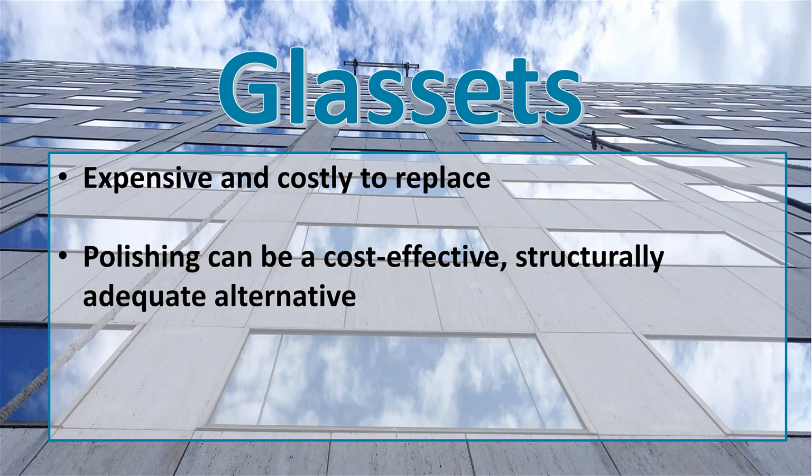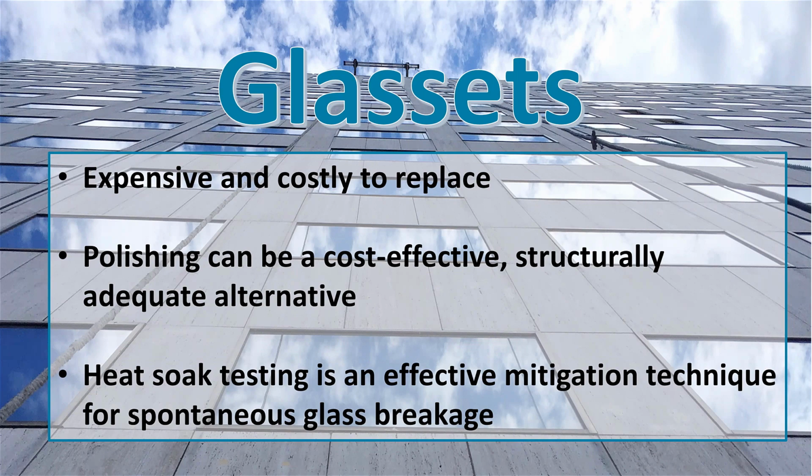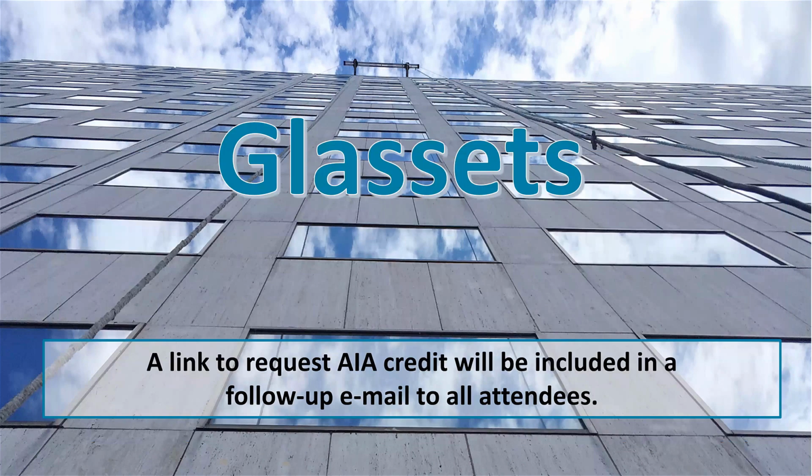And lastly, in regards to nickel sulfide breakage, heat soak testing is a very effective mitigation technique for spontaneous glass breakage. So with that, I would like to turn it over to Liz, who will moderate the questions that have been coming in.